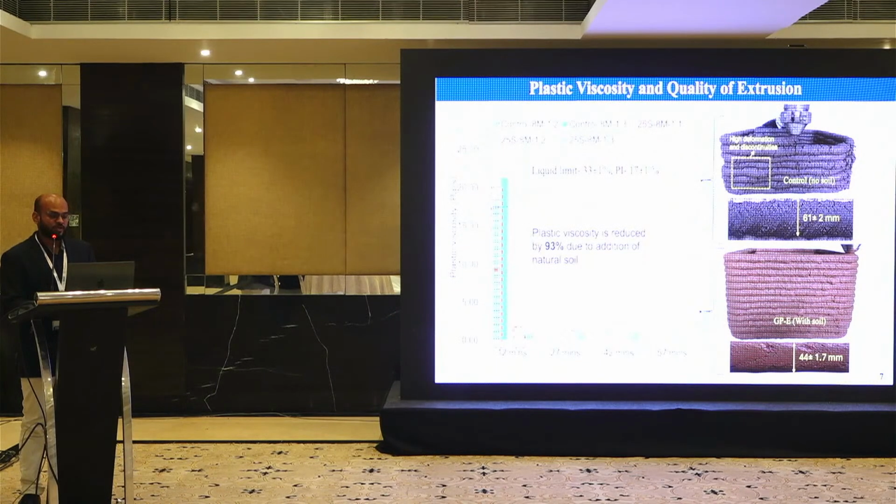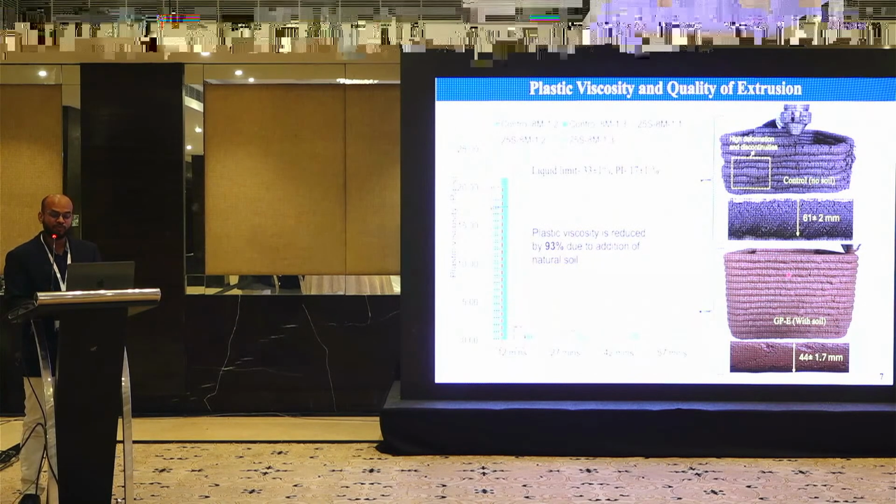There is no soil, so the plastic viscosity is very high. That is why the material cannot easily be extruded, because it creates a lot of frictional force. But at the same time, when the clay-based materials are extruded, they wrap around the surface of the sand particles, lowering the viscosity and giving a very smooth material.